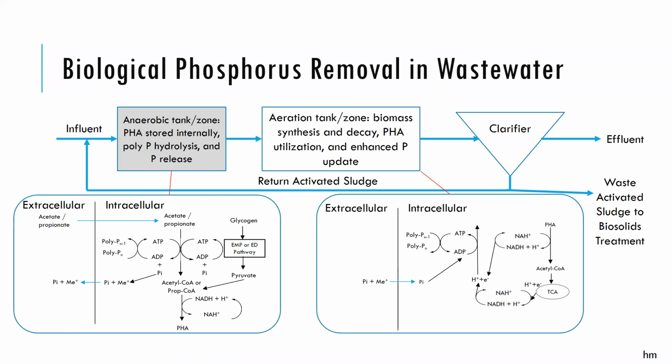So there's a lot of information here, but what you want to focus on is that this is just a simple diagram of an activated sludge treatment facility. The influent passes through an anaerobic tank prior to aeration, clarification, and the recycle. And the importance of the grayed out tank is that this is a selector. It's an anaerobic selector, which induces the release of phosphorus.